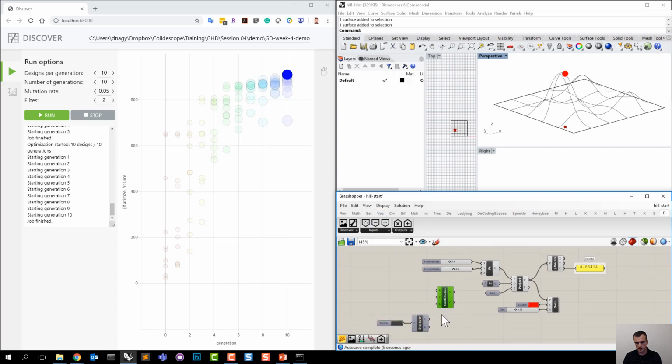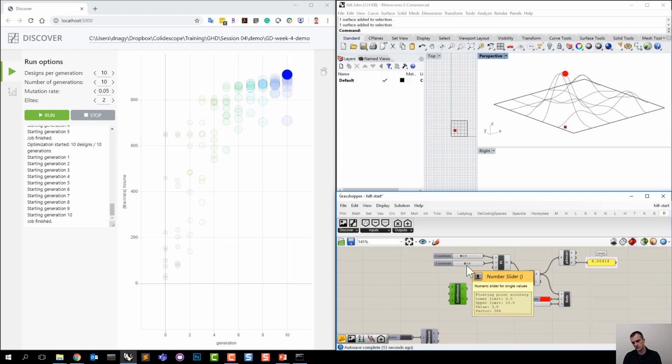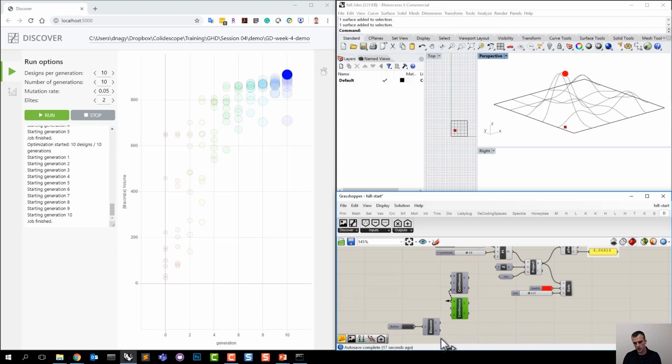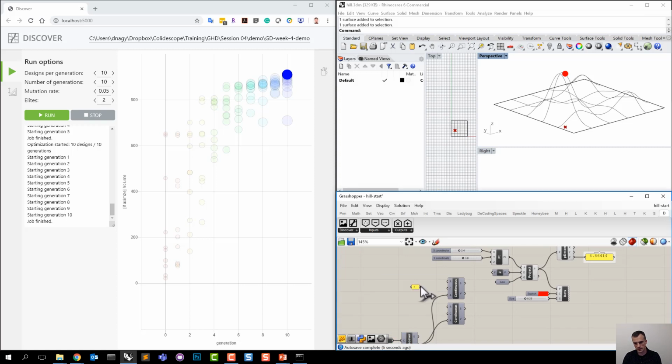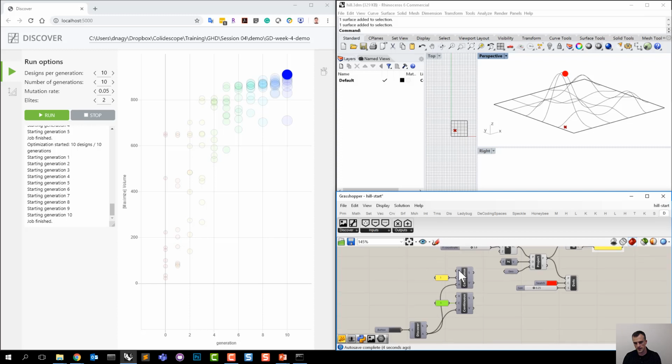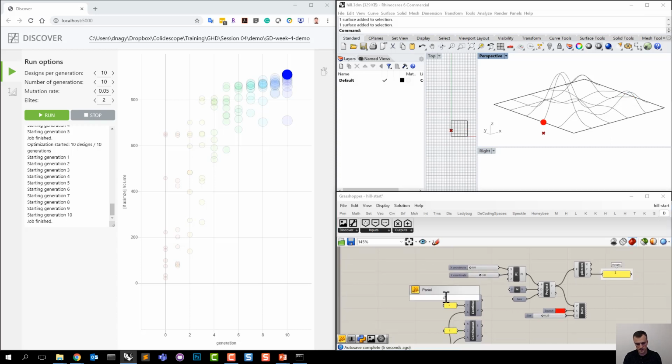In this case, I have a couple more continuous inputs, so with these ones, I have a choice. I can define them with just one input component, or I always have a choice to just create a separate input component for each one of these inputs. It's up to me. I just have to specify how many values are in each component set. So here, just to do something different, I'm going to define two separate input components, continuous inputs. The range here I'll take from my slider, so it looks like it's going from 0 to 10. So I'm going to type in 0 to 10, or if I have a range that starts at 0, I can actually, as a really quick shortcut, just type in the higher bound, and it's going to assume that the minimum is 0 because this is set up as a range input.